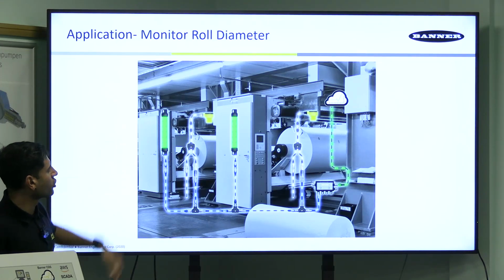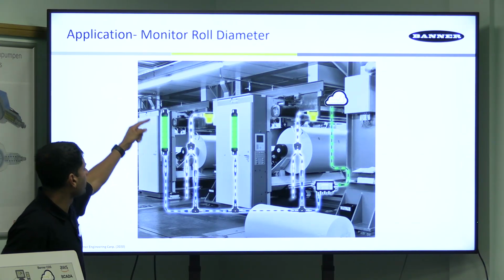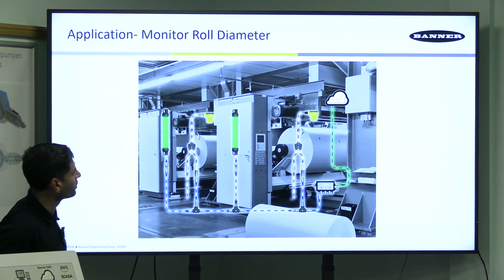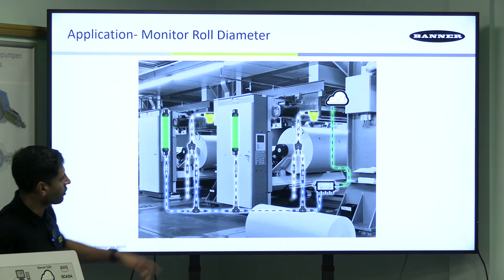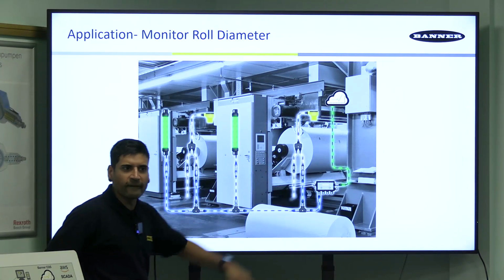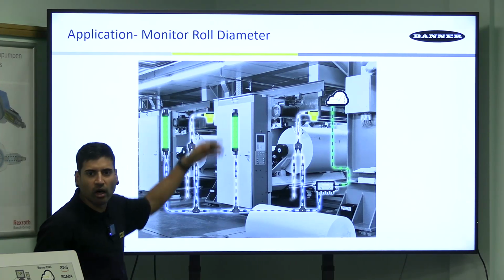So it's a good local indication. Green, the drum's a fresh drum. As the drum gets used up, the level of the light will predominantly go down. So the controller within that is taking the 4 to 20 milliamp signal and scaling it to a 0 to 100 scale, for example, on the light.